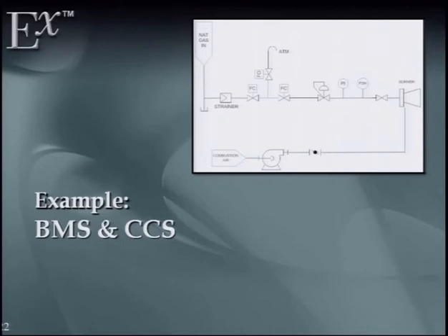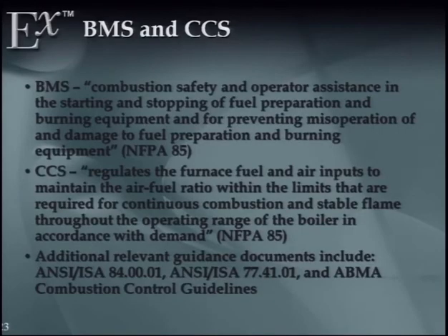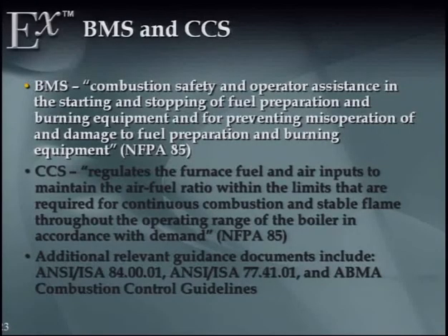Another area to focus on is the BMS, burner management system, and combustion control. These are often confused. Burner management system, here's the detailed definition from NFPA 85. It's combustion safety and operator assistance in starting and stopping of fuel preparation and burning equipment for preventing misoperation and damage to fuel preparation and burning equipment. Basically, this is the safety control system that keeps you from blowing up the firebox. So you want to safely start up and introduce fuel and safely purge after you shut down. That's what the BMS is there for.